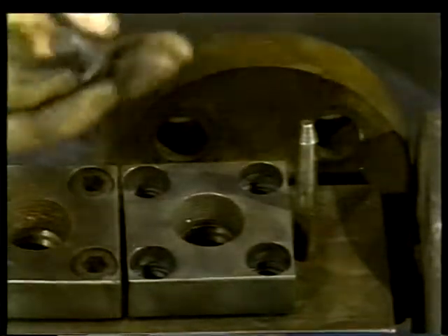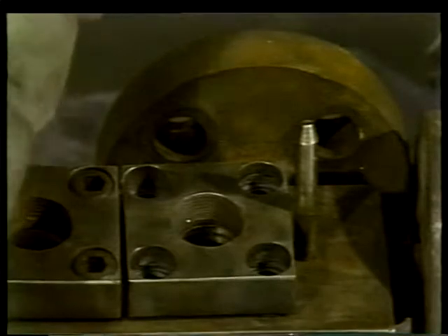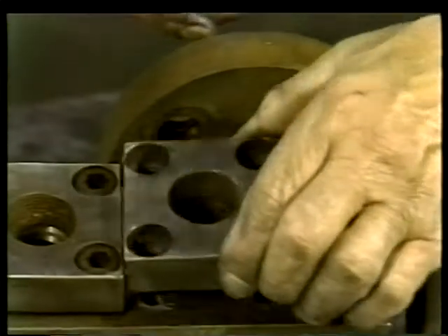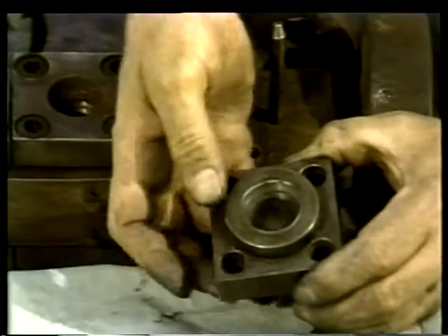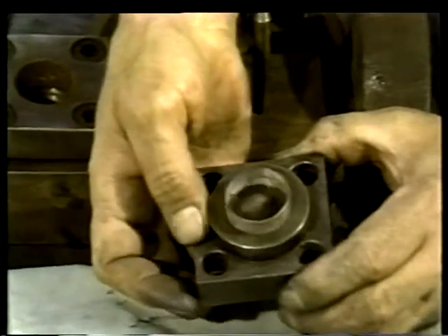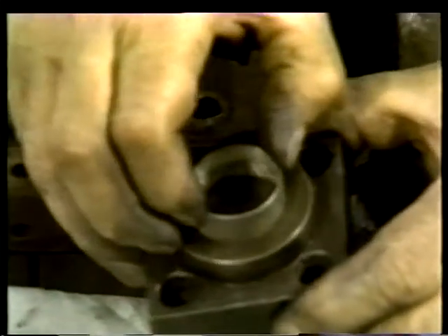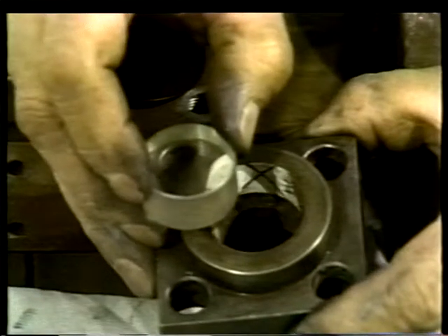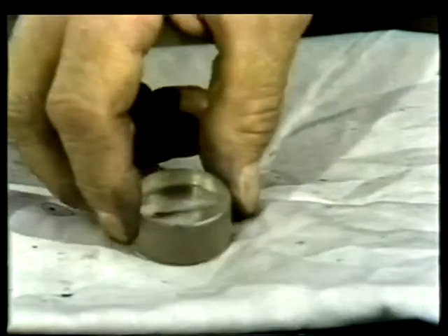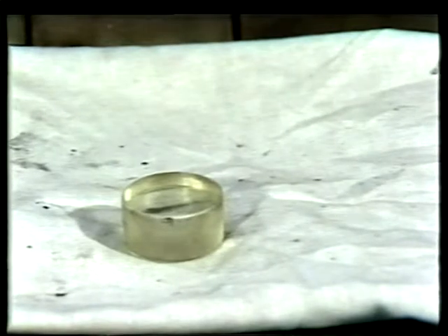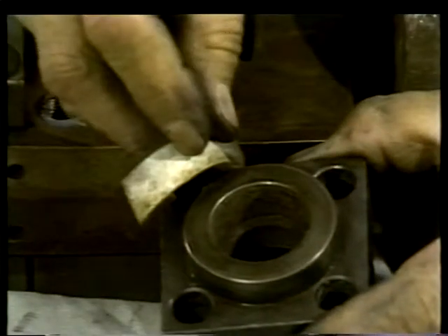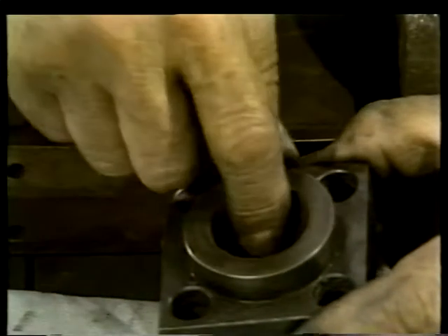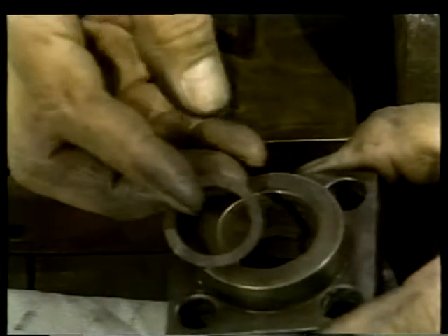Remove the cap screws from the cover plate. This will allow you to take it off. Then, remove the glass. Be careful not to put it in any place where dirt could scratch the glass's surface. Then remove the packing strip. The cushion gaskets should then come out of the cover plate.